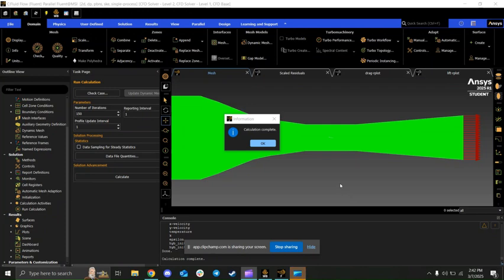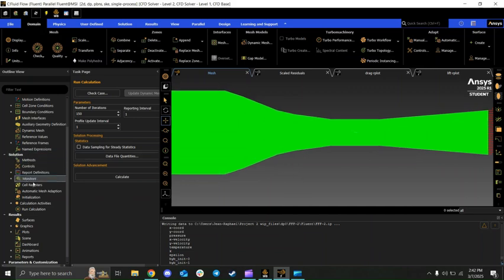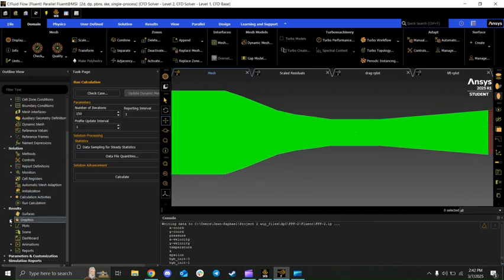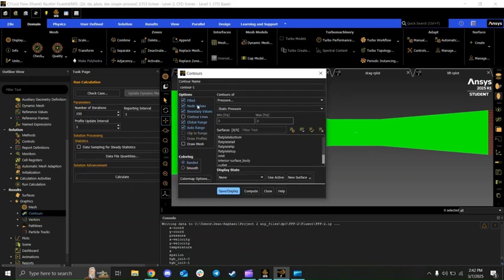All right, after a couple of minutes later, calculations are now complete. So let me have the recording, click OK. And then here we are, we got our mesh right now. So everything should be printed out here. So now to get our required plots, we go to graphics, contours. They're already here, but if you need to do it yourself, you just double click on contours.